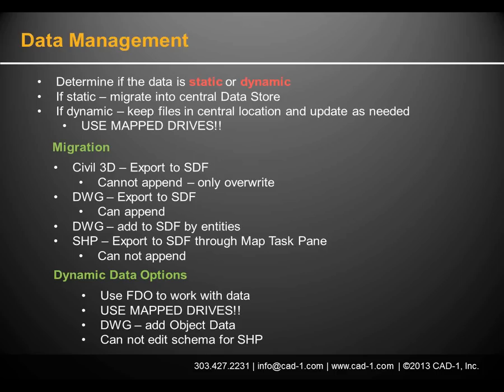All right, now, spatial data format. I'm going to go into this in great detail in another slide, but spatial data format, SDF, it's a file. It's just like an AutoCAD DWG on steroids. It allows you to add all kinds of attribute information and basically turn your drawing into a GIS system. The important thing that you're going to need to note is if you do this export right out of Civil 3D, you can't append, you can't add to an existing SDF file. It's going to create its own, so it's going to overwrite anything that you try to append to. There are workarounds, which I'm going to show you here.